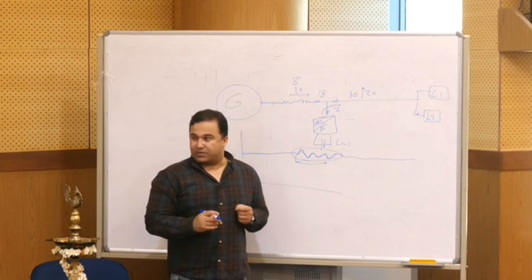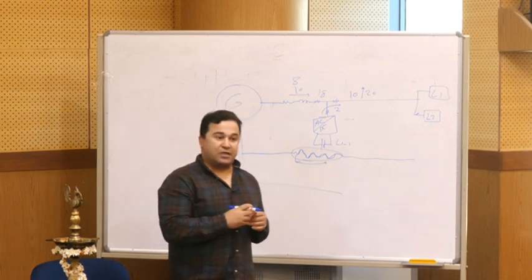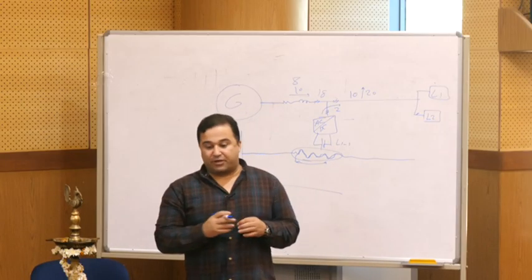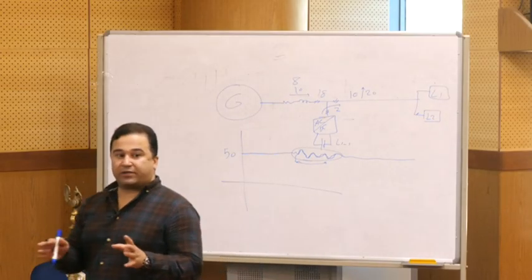These sensitive loads, like a computer or some other technology, which probably a computer is not just for playing games, you can use for programming or also monitoring lots of other things. They can tolerate the disturbance for half a cycle. In the best situation, one cycle is 20 milliseconds. So for 10 milliseconds, it can tolerate this turbulence.